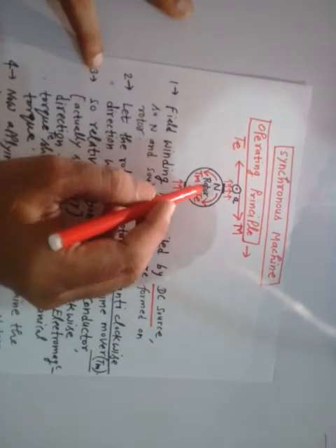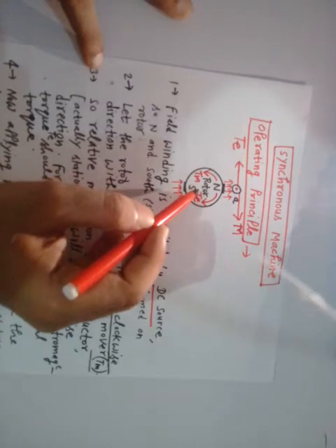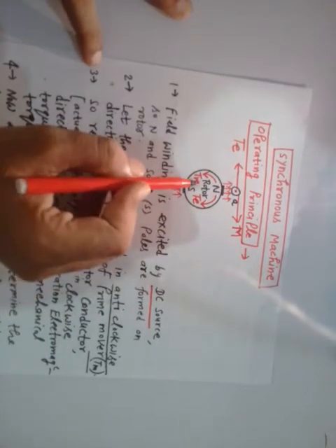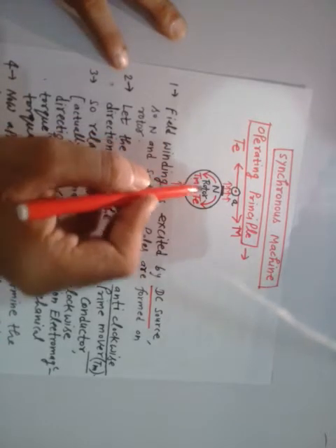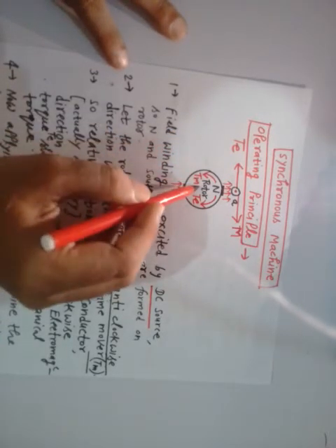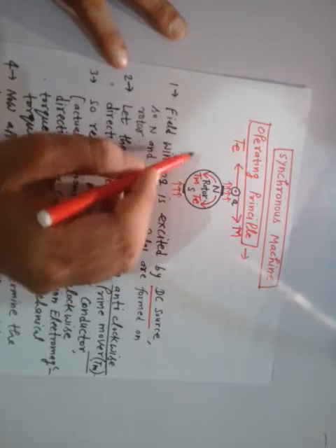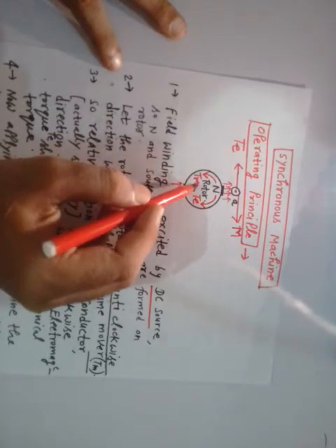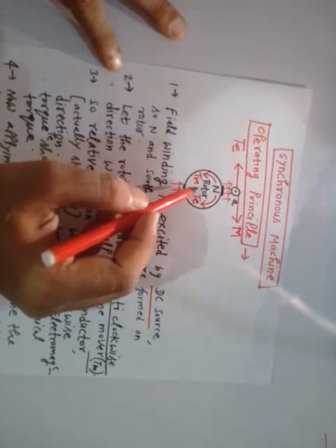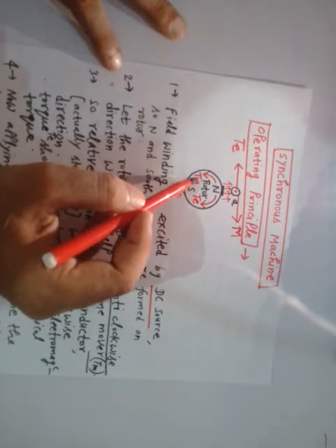As soon as it faces any decrement in speed, the steam valve will open, and some more mechanical energy will be given by the prime mover, and again the speed will be maintained constant, equal to synchronous speed.